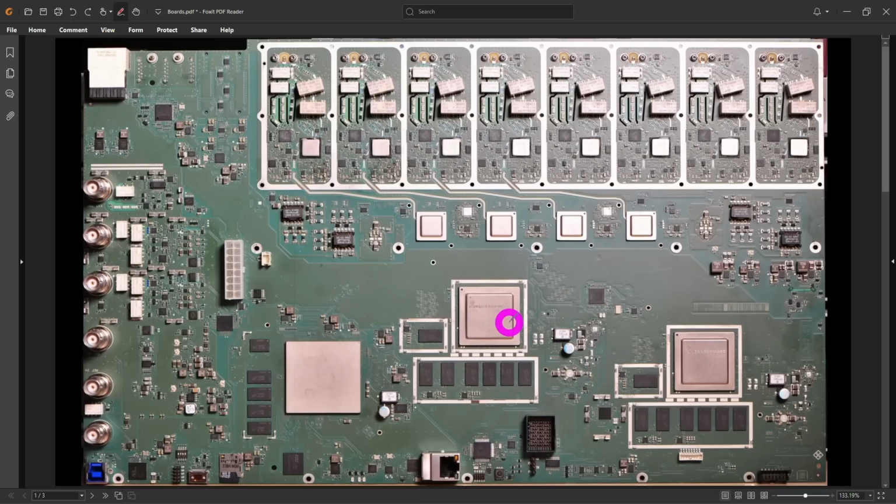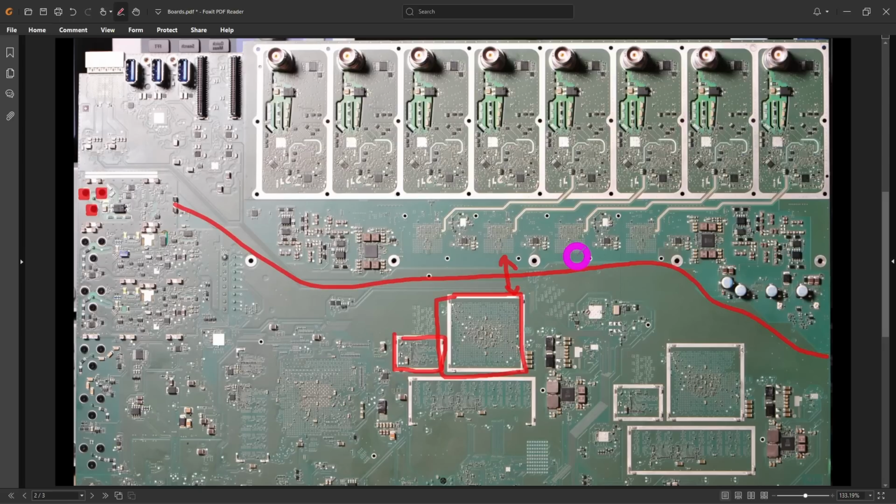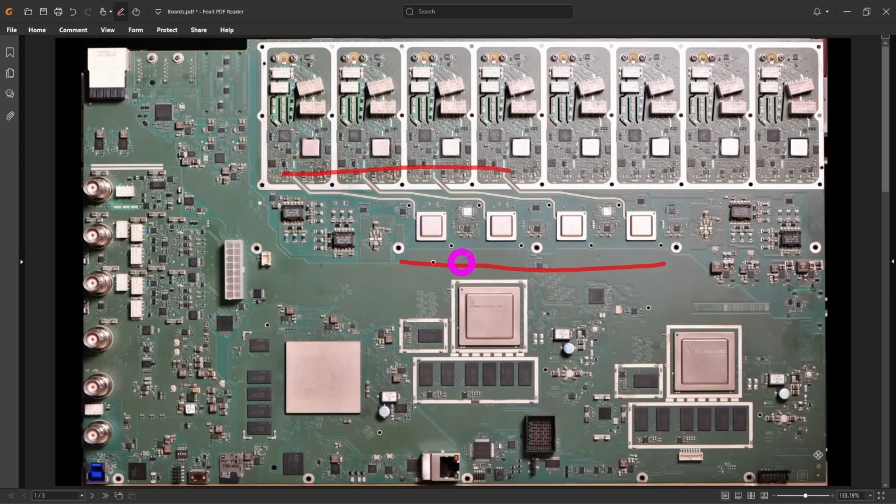And of course, a critical part of every oscilloscope is the analog to digital converter. And here we see 4 ASICs. These are custom ADCs designed by Rohde Schwarz, and each of them is a 2-channel 12-bit ADC with 10-bit effective number of bits. And if you look carefully, you can see on the left side of every channel, we are feeding the first 4 channels of the oscilloscope. And if I go to the second page, the other 4 channels are feeding the other side of the package, taking advantage of the 2-channel ADCs inside of each package. Now, even though we are doing that, each channel gets its own dedicated 12-bit ADC with no sample rate limitation, so you can mix and match channels as you want, and that's pretty important.